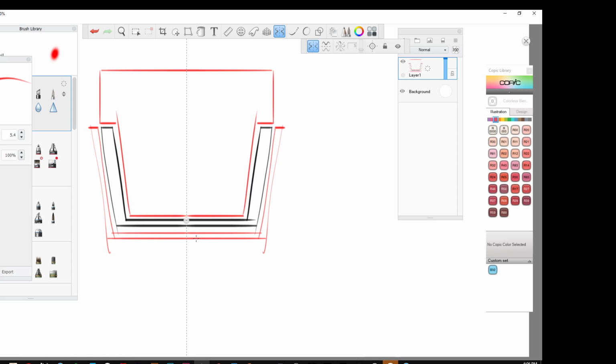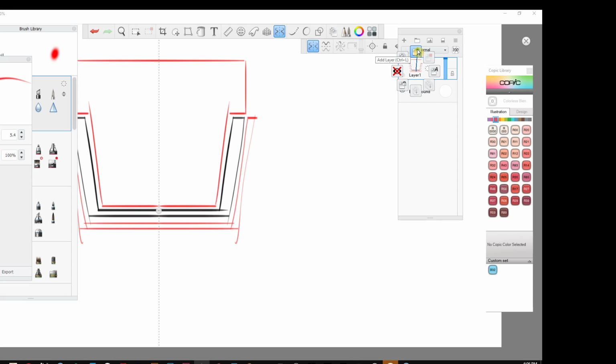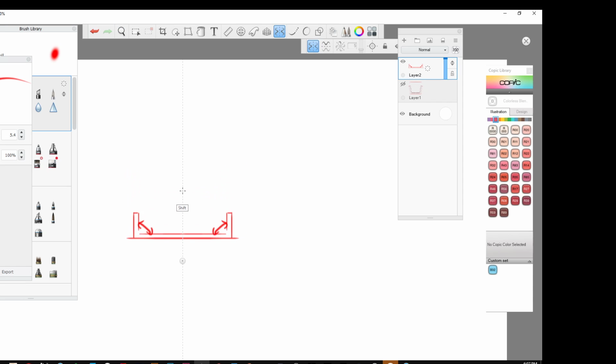Now, each plastic is a little bit different on what kind of tooling and what level of draft that you want. But a couple things that are dependent on your draft, or the angle of the draft, is that the deeper the part, the greater the draft that is needed. So if you just have a small little part like this, you're not going to need as much draft because the tool doesn't have to travel as far. So the deeper the draw, the greater the draft needs to be.